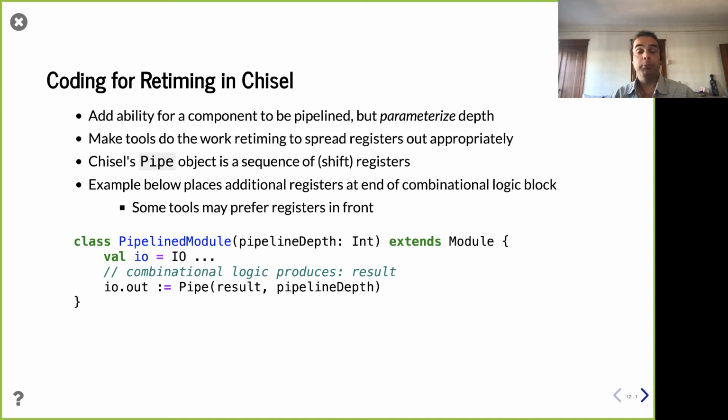And so this is one of those places where you get a real big time benefit, a productivity boost, from using something like Chisel, where you can very easily specify something like this depth for your pipeline and then use things like retiming to try and balance it, right? Retiming is a really robust feature on any reasonable ASIC CAD tool. On FPGA CAD tools, support varies, and it can be kind of cranky. For example, Xilinx Vivado, which my research group had quite a bit of familiarity with, retimes only under certain circumstances. You have to be really careful to understand that you aren't inadvertently giving it a problem that it thinks it can't retime, even though it can. It's a little bit more brittle, but cool.